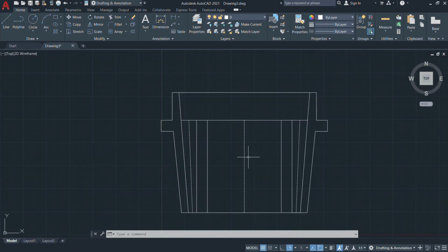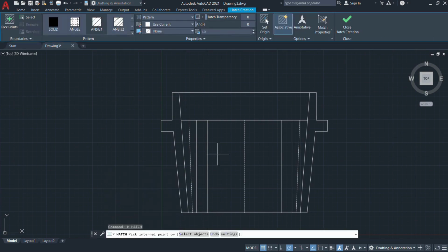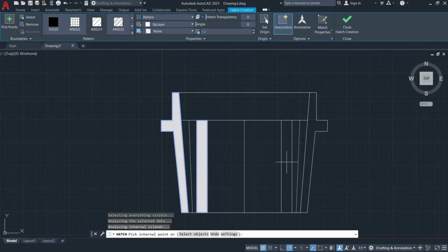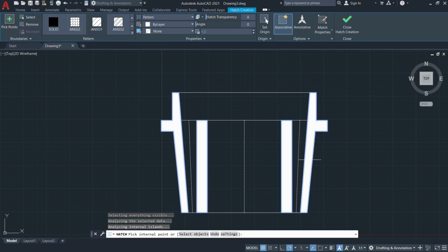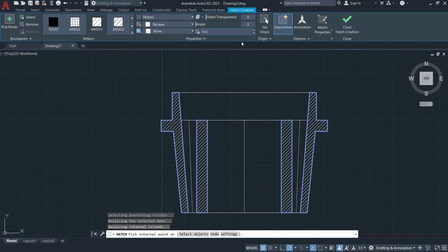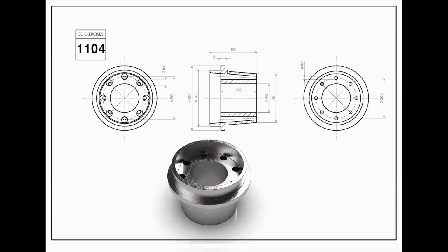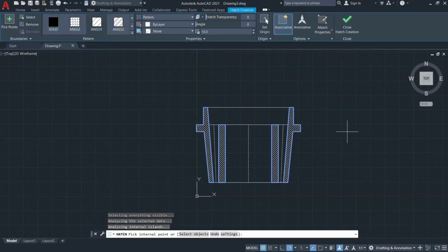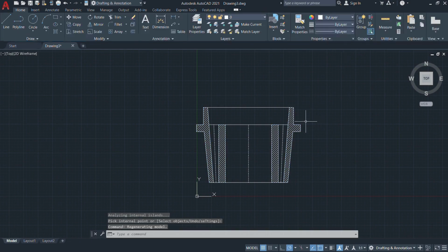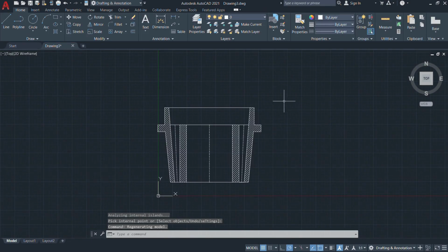How can we clearly indicate the zones? By using hatches. Type the command H and choose whatever closed portion we need to apply the hatches. Once we have selected it, increase the scale number, and only then can we give it in a complete way. Once I increase the scale ratio, automatically the hatches are represented on this area. Now the front view is clearly drawn.